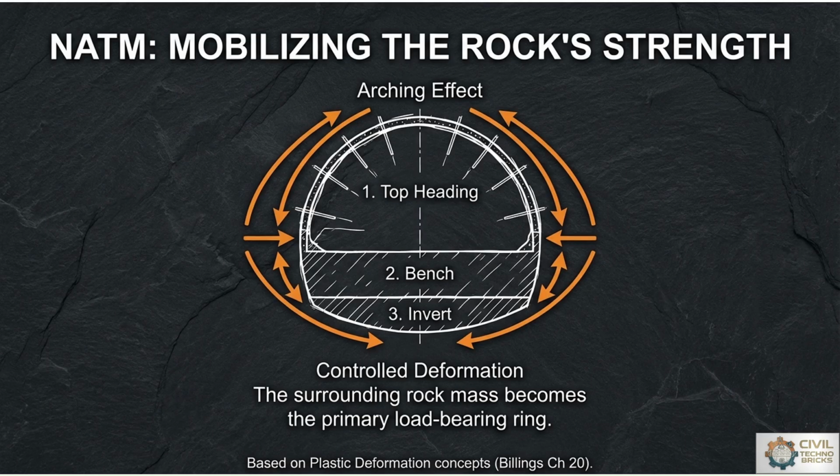If we have rock strength, then it is easier to construct a tunnel. It may be by using the drill and blast method, or it may be by using tunnel boring techniques. So rock quality determines the stability and support requirements of tunnel excavation.